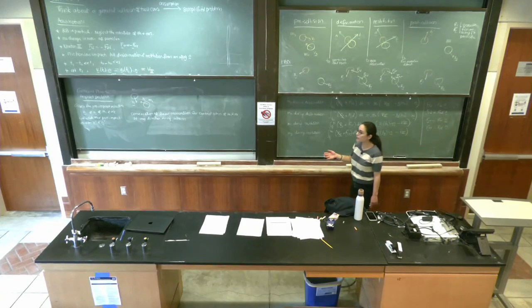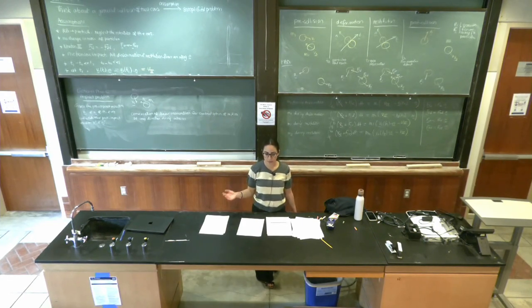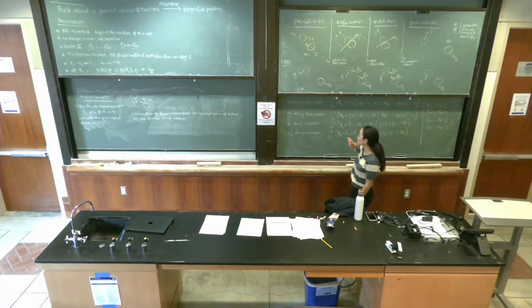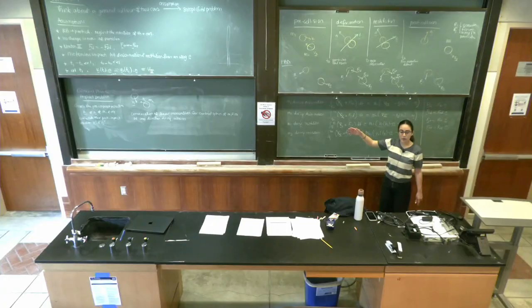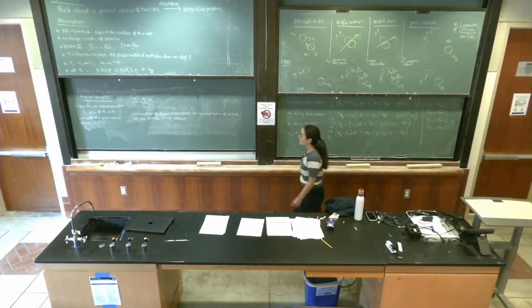In this problem in particular, the normal and the weight force are perpendicular to the page, along the vertical direction, and there's no acceleration in the vertical direction, so they sum to 0. So we don't even need to make the assumption that they're smooth. However, even if we do make the assumption, the impact forces cancel out for the combined system because of Newton's third law. All the smooth forces, their impulse is almost 0. So it is true that for the combined system,